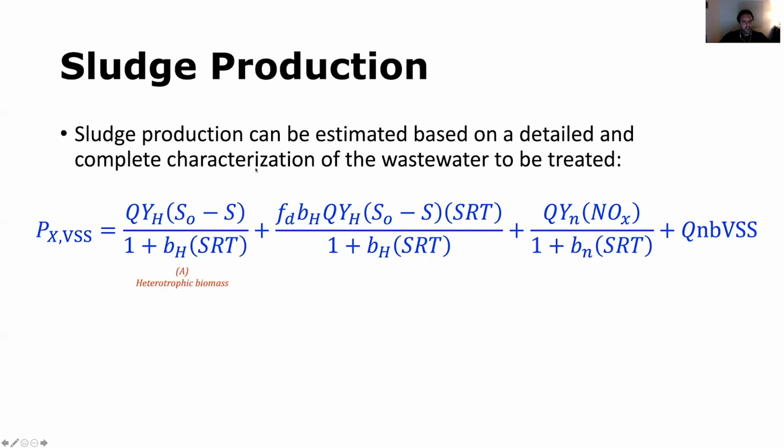All right, so this first term in the equation represents the sludge that corresponds to heterotrophic biomass. Heterotrophs are those microorganisms that are degrading carbon compounds to CO2. The second term here represents cell debris. So these are the decayed microorganisms after they're no longer active and their cellular biomass is starting to be consumed in the system, but there's some that will remain. It's not degraded, it's not reused in the process, and that remains as cell debris, which is this term right here.